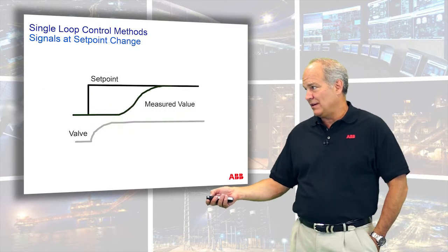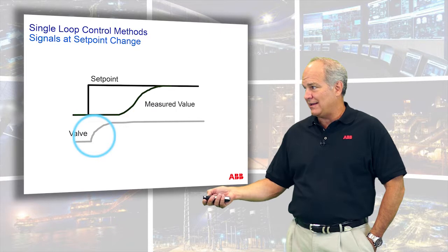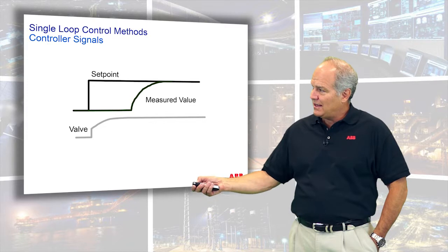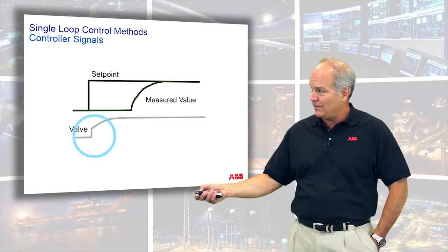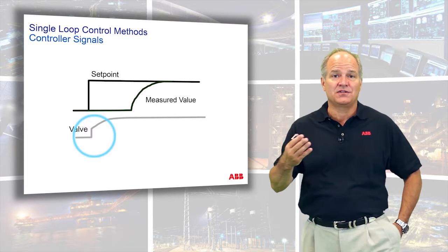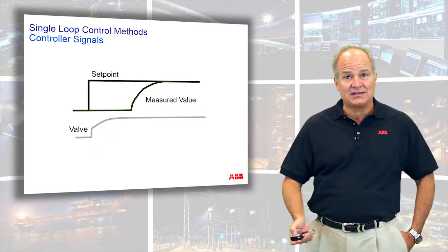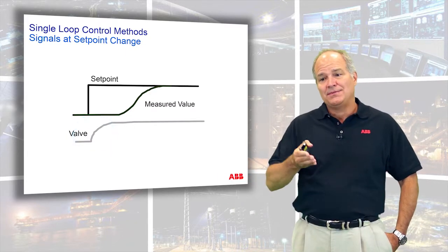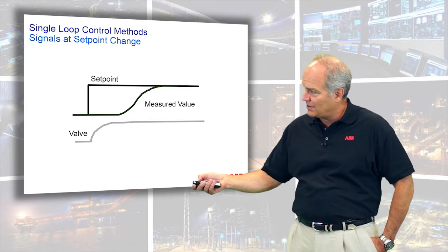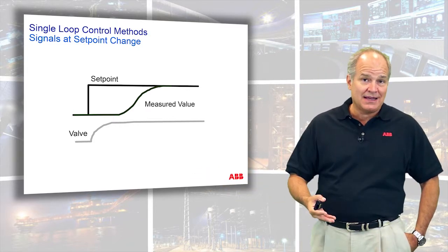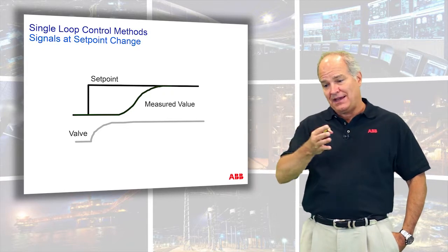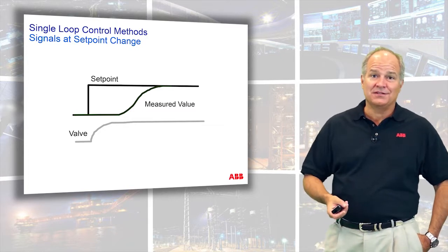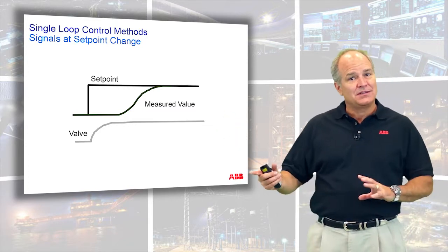One of the issues with that early technology with the integral only is you don't get that kick. If I go back a couple slides here, when I change the set point on a Smith predictor, I get this kick. It's a function of your tau ratio, so your closed loop response is faster. On a modified Smith, you don't get that kick because it's an integral only control. So what happens is it's a little bit slower. Notice you kind of get this S curve in the measurement. It's a very stable control, and on those early applications, that's what we wanted. So this worked great, and actually that control has run for over 30 years. So it's not a bad idea, but it's a little bit slow.